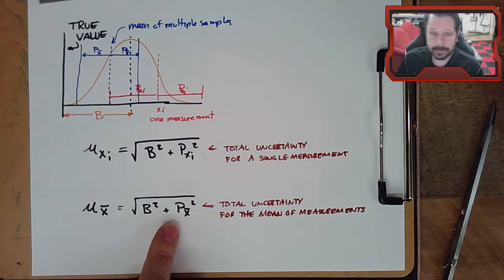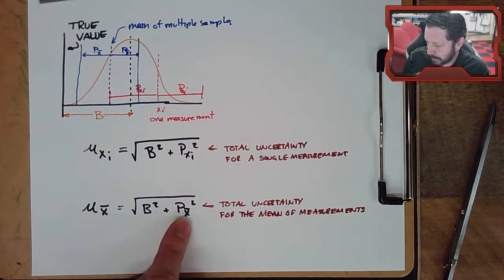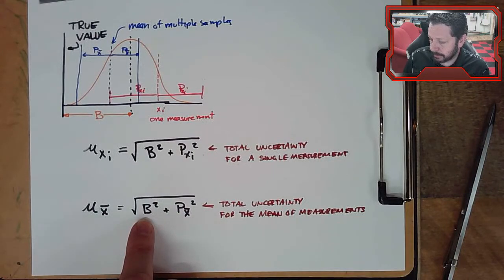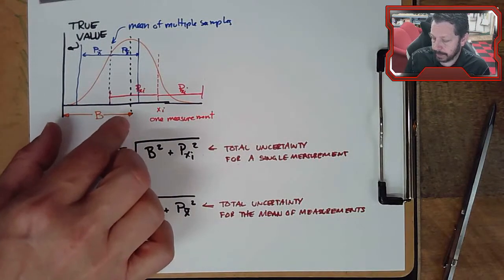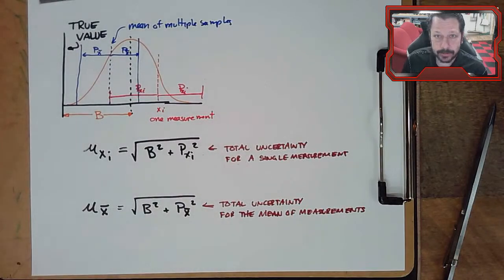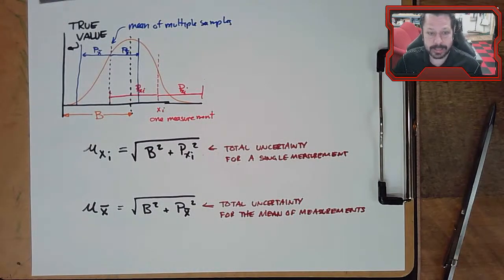So here you've taken, say, 10 or 15 measurements. You've calculated their mean, their standard deviation, and a t value from the chart, and you've calculated the uncertainty around that mean. Then you've combined it with this offset that you may or may not know about. The offset you would have to know from a bigger data set or from some other information.